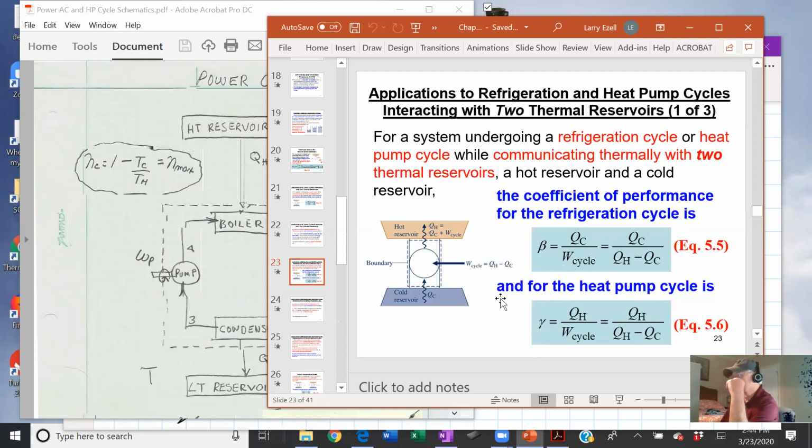I don't think I finished the heat pump. Anyway, for a heat pump, this would be the area you want to heat. It actually pulls heat from a cold outside. Say it's 40 degrees outside and you want it 70 degrees inside. Well, it's actually able to absorb some heat from outside, even though it's 40 degrees, because its fluid is colder than the outside air. The fluid is, say, 35 degrees Fahrenheit and the outside is 40, so it's able to pull some heat in from the outside and store it in the fluid.